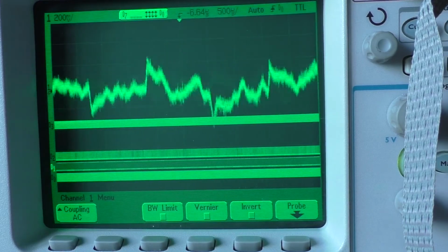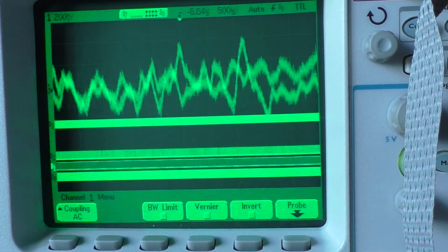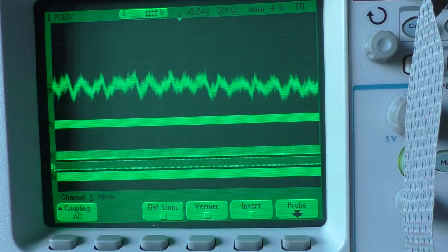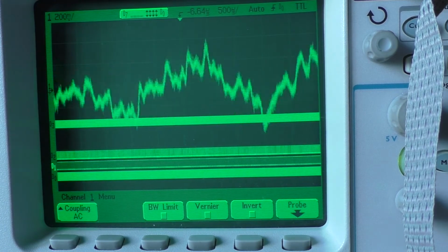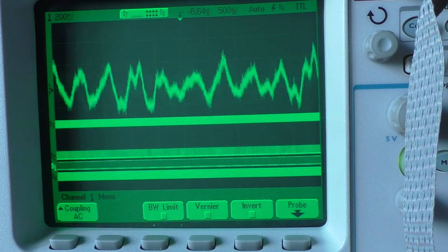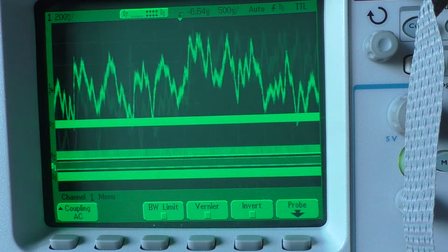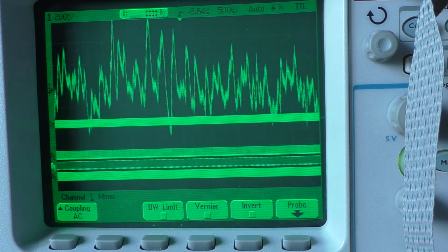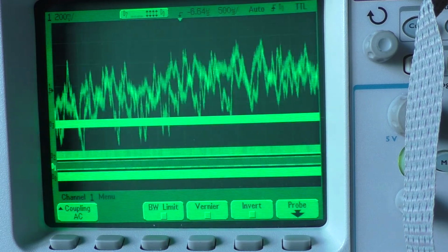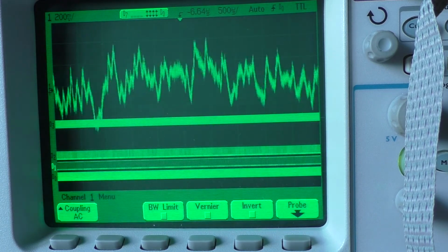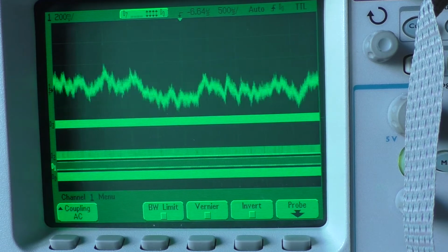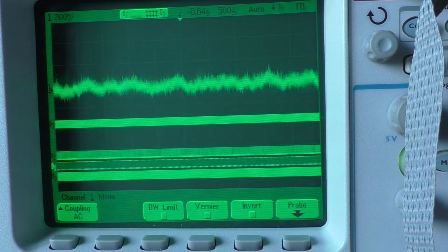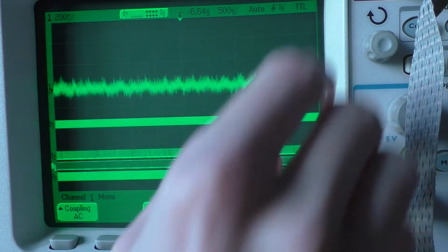And so we have arrived at the actual analog output. I've turned channel 1 back on and I'm sampling the analog output from the DAC. This is one of the signals for the right channel. As I said, this is a stereo differential DAC, so it creates 4 analog signals, and then these signals are simply fed to the analog frontend, which drives the headphones. And as you can see, the frequency of the audio signal is quite low compared to the frequency of the sample clock.